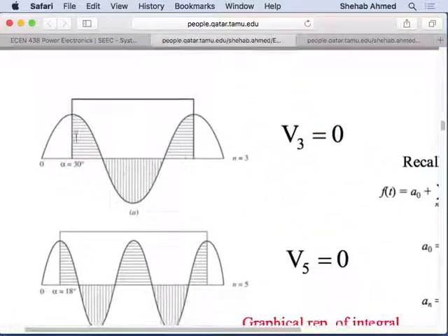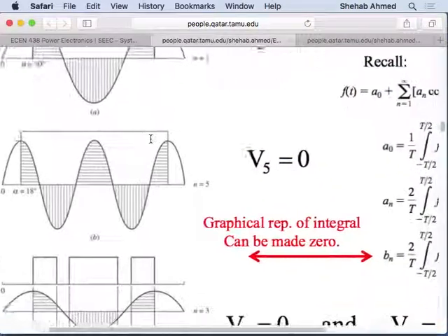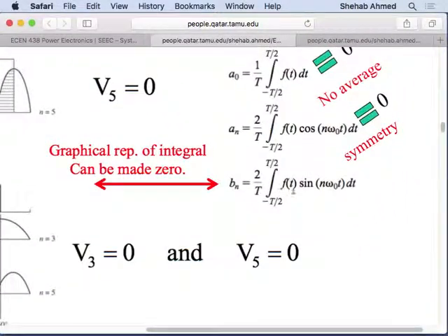If I multiply them by each other, assuming this here has a peak value of 1, then the multiplication here will be 0. The multiplication here will be 0. And the multiplication within this period will be the sine wave, the same shape as the sine wave. It's scaled up or scaled down, doesn't matter, depending on the value of this. If it's 1, then it's equal to the sine wave. So this is the area under the curve of the two waveforms multiplied by each other. This area under the curve is the multiplication that I have here.